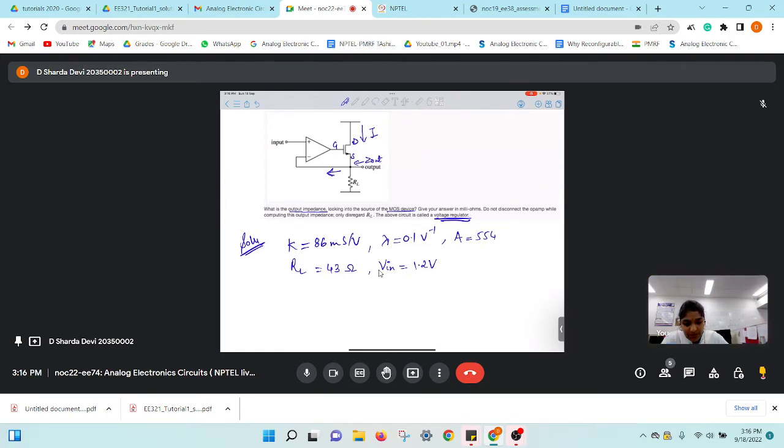So will it be 0 ampere? 0 ampere, right? So here it will be 0. Why? Because the current entering the op-amp is 0. So we only have one single current path, so a single current will flow through this MOS device as well as this resistor,